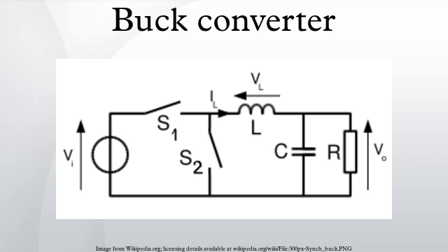Where Zo is the output's impedance, Zi is the input's impedance, substituting these expressions for Io and Ii into the power equation yields the following, as was previously shown for the continuous mode. Where D is the duty cycle, substituting this equation for Vo into the previous equation yields, which reduces to the following. And finally, this shows that it is possible to adjust the impedance ratio by adjusting the duty cycle. This is particularly useful in applications where the impedances are dynamically changing.